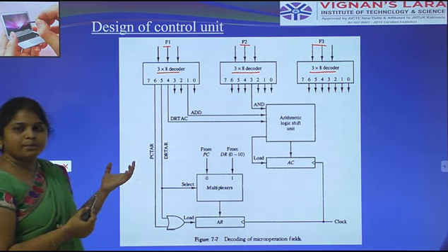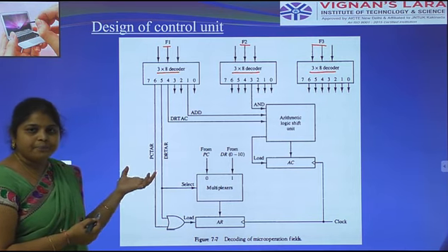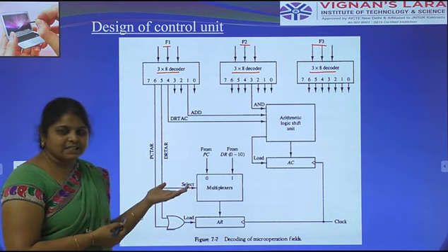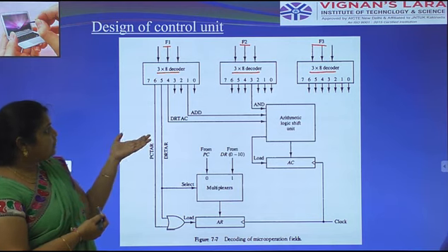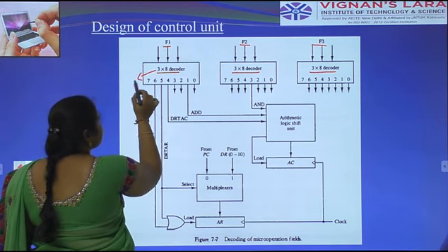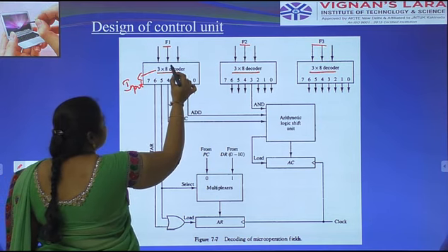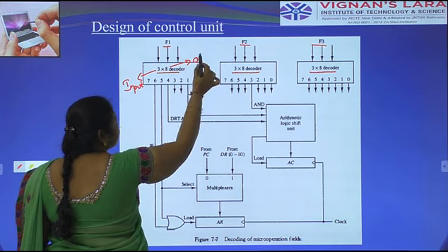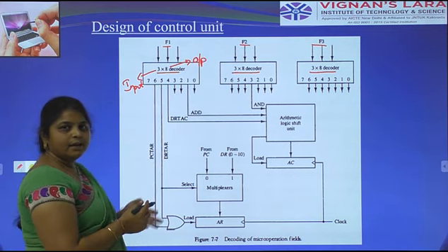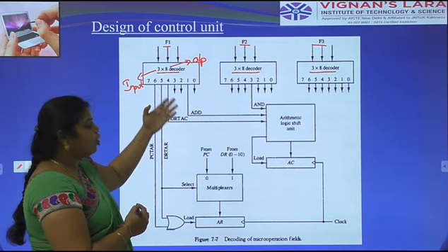In the last class we saw the microinstruction code format, which contains field 1, field 2, field 3, and address register, data register and accumulator. Field 1, field 2 and field 3 contain 3 bits. Here the input is 3 bits, and 8 means output. Here we have to take a 3/8 decoder, where 3 means input lines and 8 are the output lines.